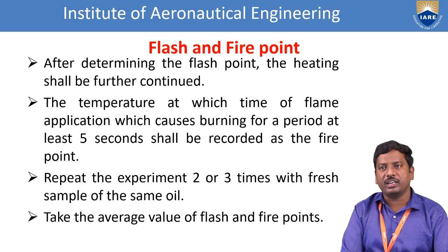So that means after the determination of the flash point, the heating shall be continued. The temperature at which the flame application causes burning for a period of at least 5 seconds is nothing but the fire point. Okay, so this is the determination of flash and fire point.